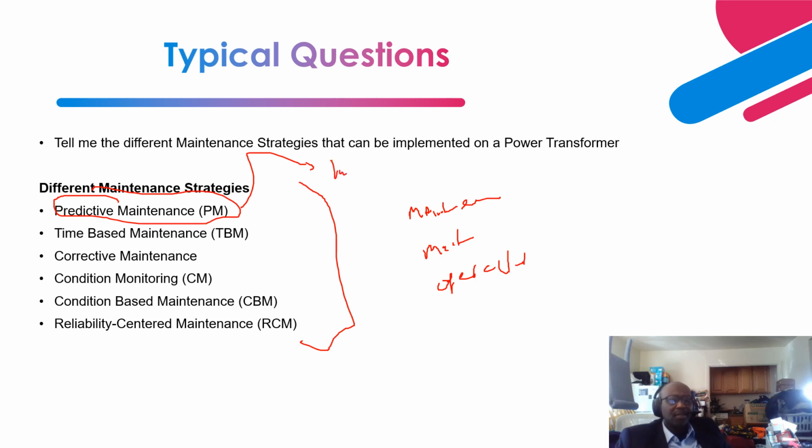The first one is infrared thermography, right? Okay, so depending on the maintenance cycle, we have a yearly or a 6-month maintenance cycle that is implemented as part of the maintenance strategy and cycle, right? Where basically you go to the field and perform a thermography scan to identify hotspots, right? Then based on that, you review the hotspot signatures to identify and implement the corrective actions, right?